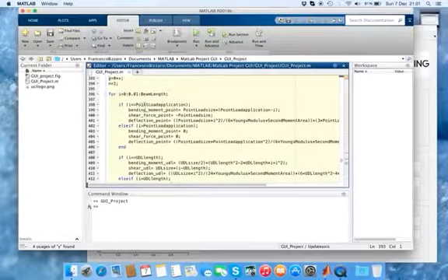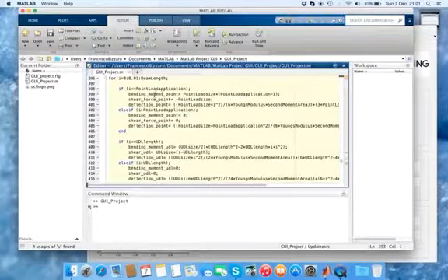And we use the principle of superposition and find the bending moment, shear force, and deflection at each point, of the point load and the UDL effects separately. So these are the simple equations that can be derived mathematically, and obviously considering a point load alone, once the x value is past the point load application, there would be no bending moment and no shear force.